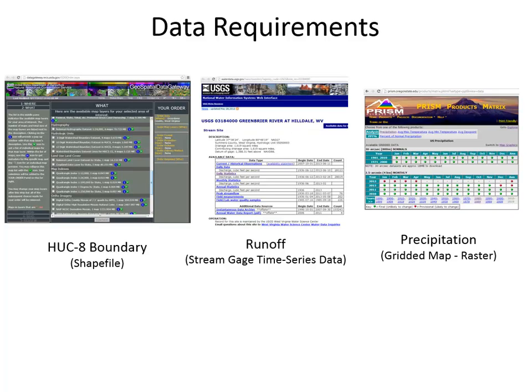What I did in this project was I used a couple of different data sources in order to define the watershed boundary, for example, online. I don't know how many of these websites are going right now, but over the summer anyways, you could get the HUC watershed boundaries online, and I also compared those pre-delineated watershed boundaries to the delineation model I've shown to you before,